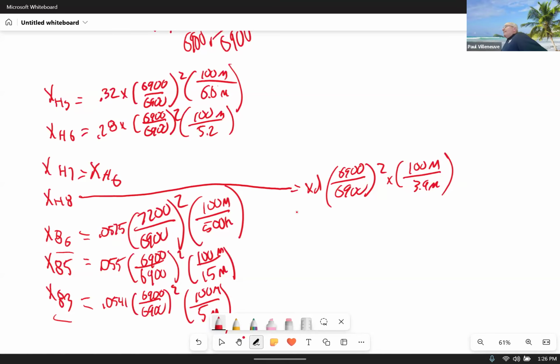And that was the per unit diagram, converting everything to per unit on a consistent base. And we sort of did the whole process, right? We identified S base, one V base, and then we calculated all the V bases. The extra thing that we had to do here is we had to go ahead and get the data, and that's what you'd have to do in the real world. Somebody's not going to say, here, convert this diagram to per unit. They're going to say, go get me a diagram in per unit and make sure it's all on a consistent base. So you're going to have to retrieve all the data to put it together.